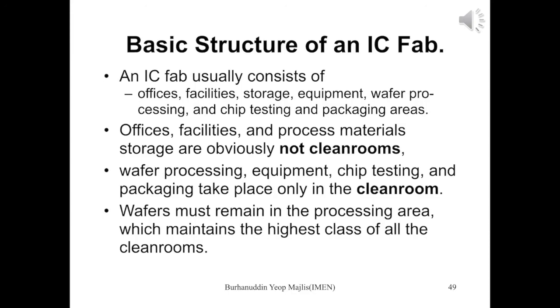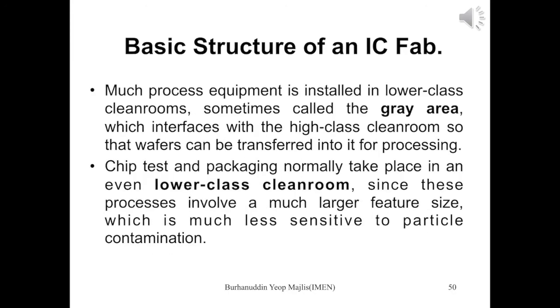So the wafer must remain in the processing area, which maintains the highest class of all the clean rooms. So most of the process equipment is installed in a lower class clean room. Sometimes it's called the gray area. The gray area interfaces with the higher class clean room, so that wafers can be transferred into the clean room for processing.